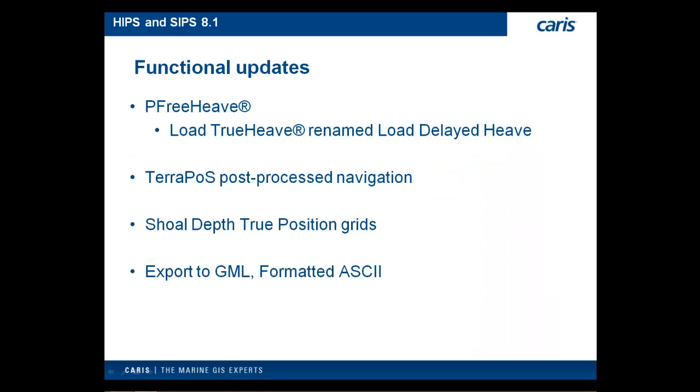So we've done some work on the functionality side as well. Although I won't be demoing too much of this, we've added support for 2 new post-process formats, POS-Pac Heave from Kongsberg and TerraPos post-process navigation. And for the post-processed heave, we've renamed the Load True Heave dialog to Load Delayed Heave, making it a little more generic than it was previously to reflect we support more than one format.